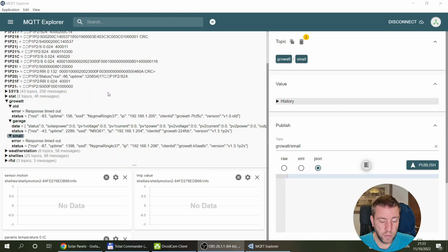I'm recording this part of the video in the evening, so I can't really show you too much on the inverter side in MQTT, because all the inverters are sleeping at the moment, there is no PV output. For some reason, I'm still getting data from one of the inverters, but not from the others. They just turn off, so there is no response on the Modbus line. I really don't know what the difference is. They are more or less the same Growatt inverters.